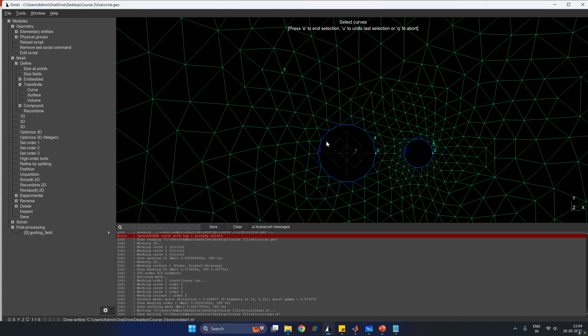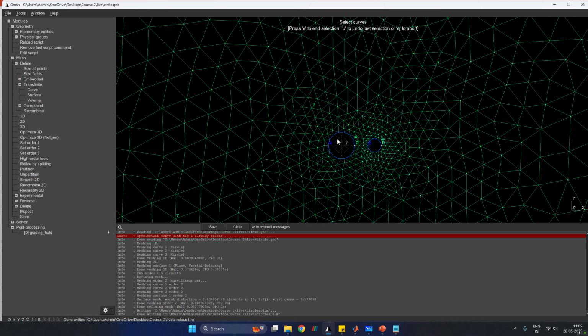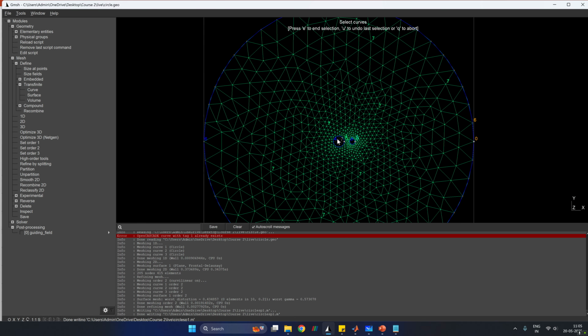So the stress is basically a tensor which is contracted to a vector, and so it has x and y components. In this case, your flux is a vector which is dotted with the unit normal. In case of Navier-Stokes, the stress tensor is dotted with the unit normal, and that tensor just shrinks to a vector. So we'll see all of that in the next course, which is on Navier-Stokes. So let's not bring that here.